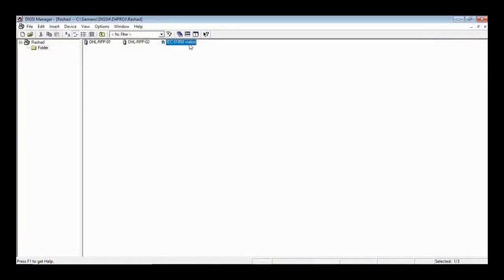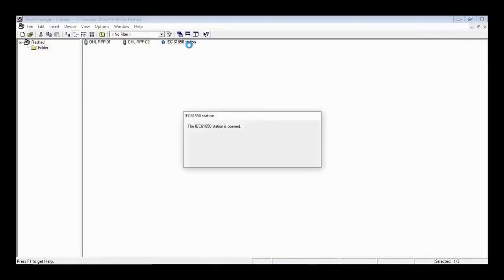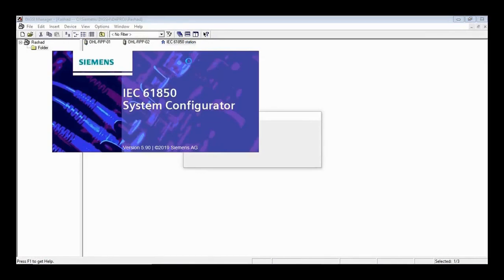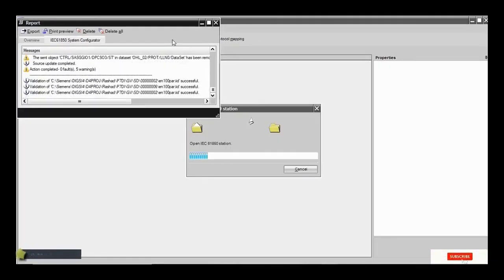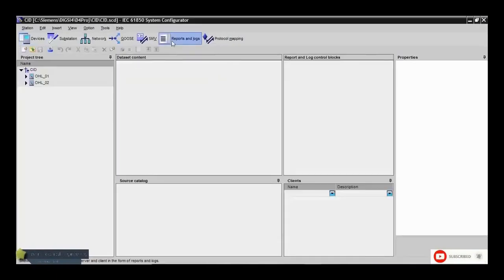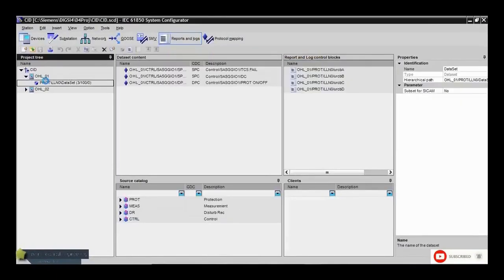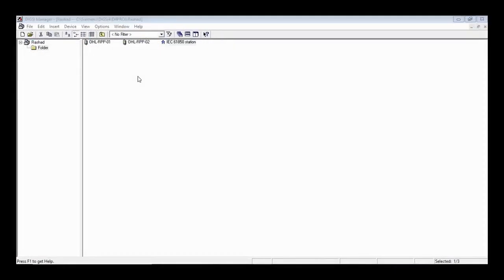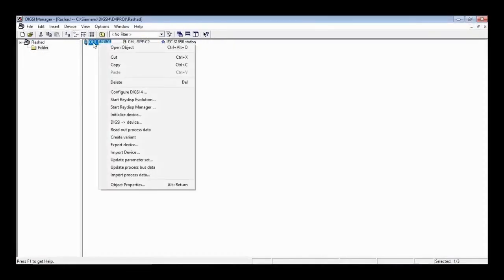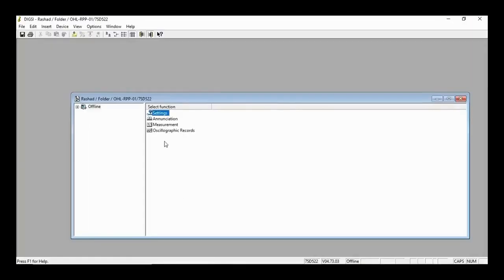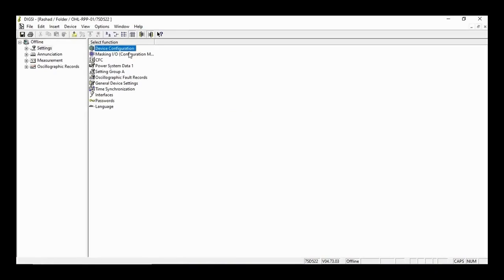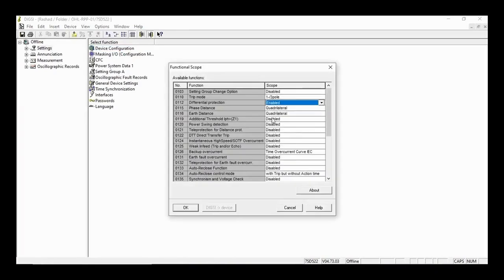When you decide to open the IEC 61850 standard once more, and we proceed to navigate towards our specific report section, ensuring all necessary details are covered. Oh, it brought you 3 warnings. If you open this state, you will find 3 signals here that were related to the differential second harmonic, which have disappeared. So even if you go back and open your settings offline and enable them again, your signals will not return. You will have to put them back into your CID file.